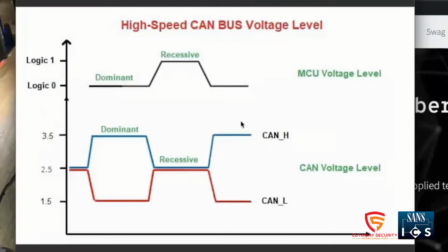So earlier I talked about how cars are electrically noisy environments. So if we're looking at this diagram and think, what would happen if there was some kind of big spike on the line or noise on the line from something? Because you've got this differential pair, if we've got a big spike here and we have the same big spike here because these are twisted together, it's going to come out in the wash because the devices listening on the CAN bus are looking at the difference between the two and not the absolute voltages. So if you have a big spike on one, you're going to have a big spike on the other. You're just looking at the difference and it's going to come out in the wash, which means that you've got a way to withstand that noise. You don't have to rely on the car being an electrically nice environment for the ECUs.